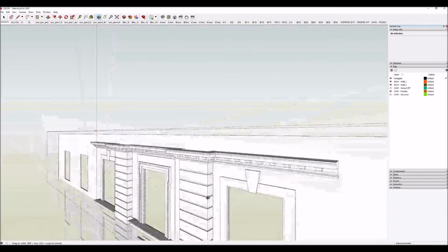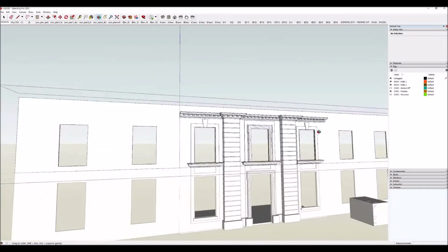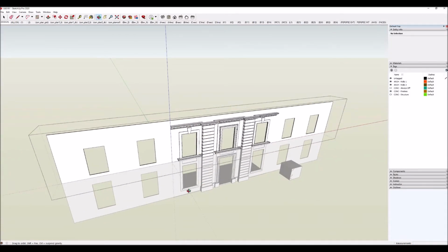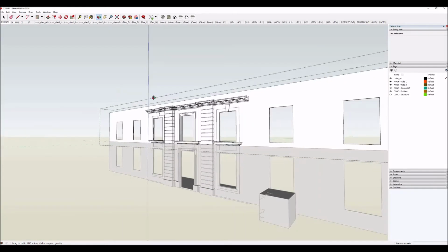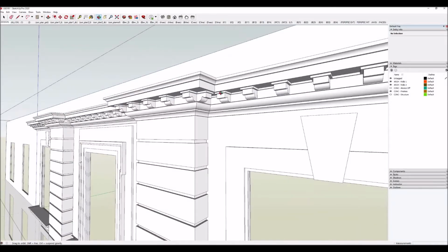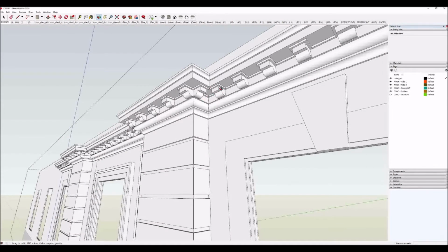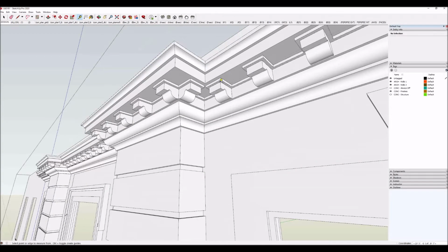And that brought up an interesting relationship between the parts here. If you're laying out a structure like this and you want to have that cornice wrapping around, and perhaps you've got a wing that bumps out and then steps back, you will want to consider the module, the typical distance between these brackets, and use that module as your dimension. So if I wanted to bring this out further, I wouldn't just go another 2 or 3 inches or something. That would leave me with just a mess of conflicting brackets again. What I would do is take that center to center dimension. Let's see, what is that?